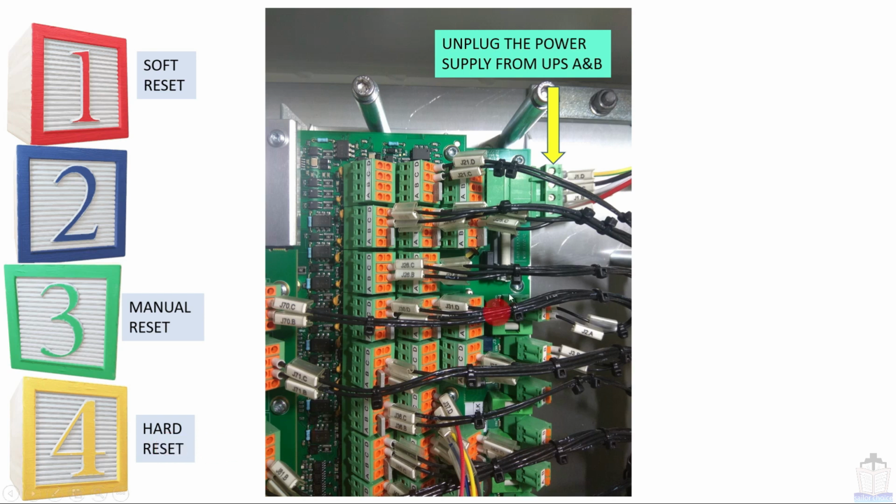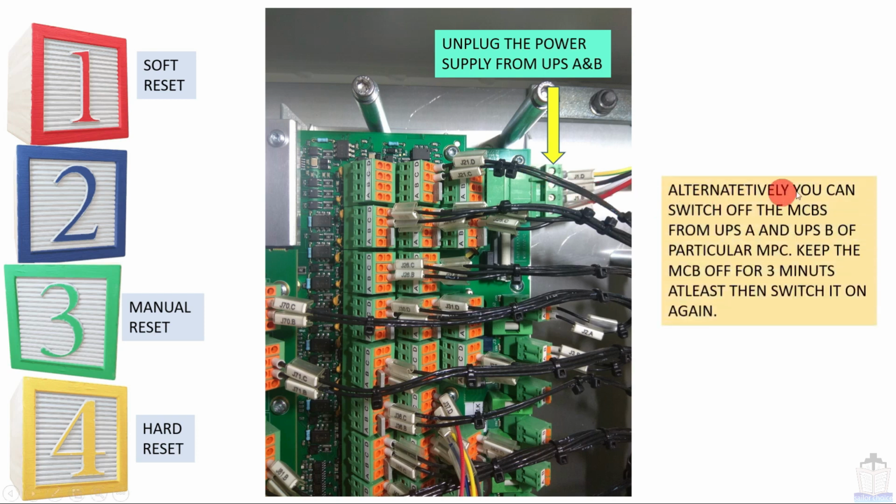Hard reset means you have to take the power supply off from this whole MPC board. That means you are disconnecting the power of the MPC. So unplug the power supply from UPS A and B and keep it for 3 minutes, and then you reconnect it, and by doing this your MPC will be reset. Alternatively, you can switch off the MCB from UPS A and UPS B of the particular MPC, keep the MPC off for at least 3 minutes, then switch it on again. So there are 4 methods by which we can reset our MPC if it hangs.